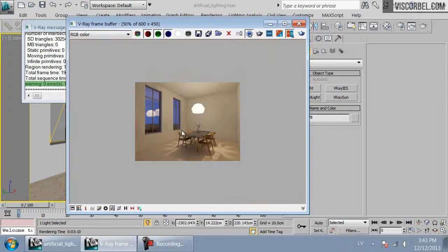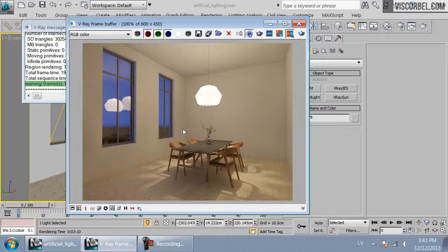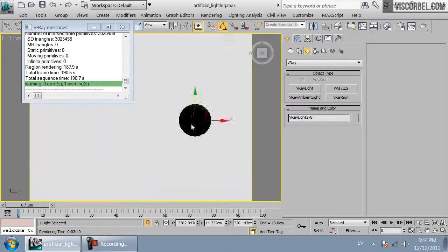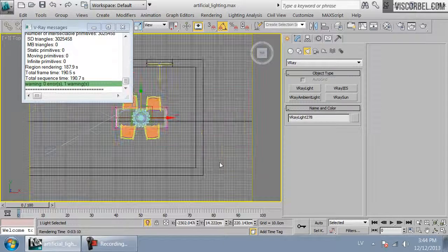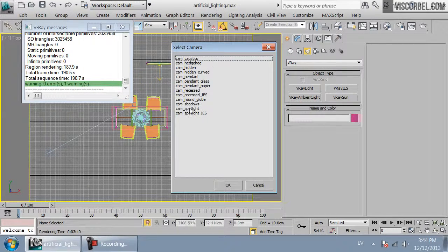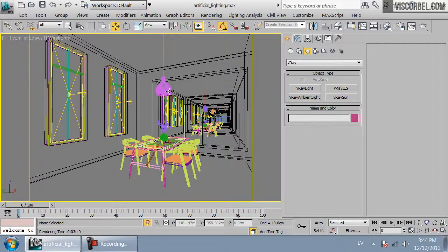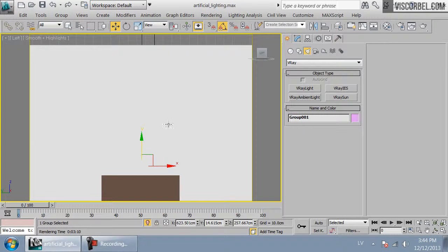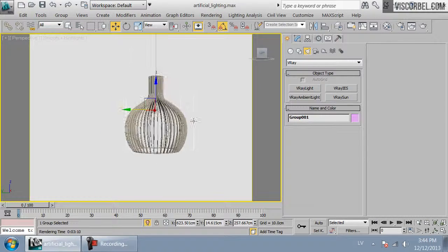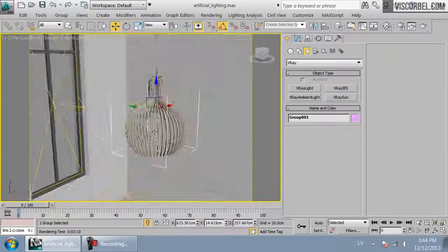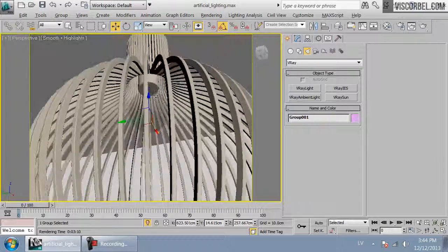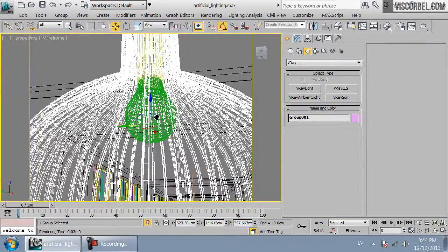Okay, so in my opinion, vray two-sided is one of the best options if you need quick renders and if you have a lampshade made from cloth or paper. So next up, I'm going to show you a lamp that presents some different challenges. Okay, and in this case we have this lamp where the light bulb is directly visible, and I actually modeled it roughly.